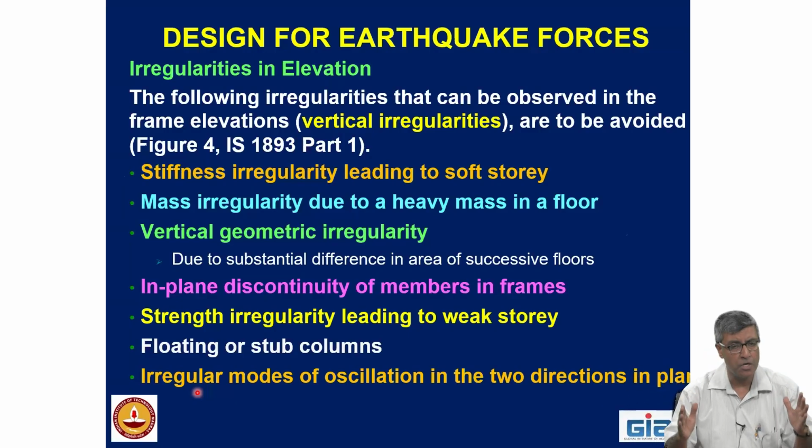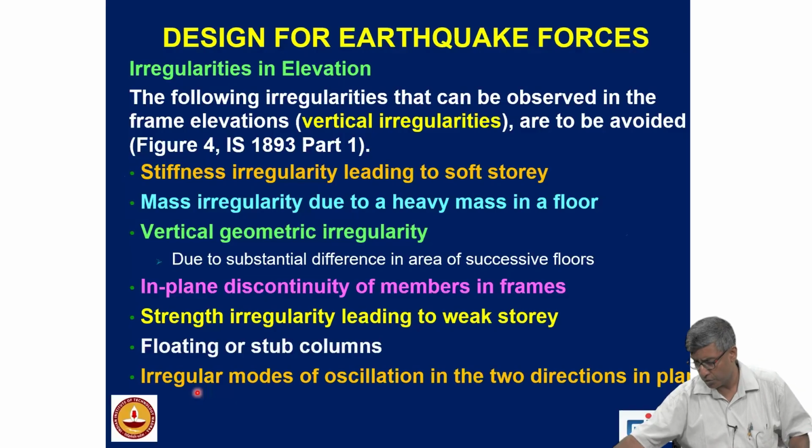I will repeat that we should have at least 2 frames in the 2 orthogonal directions, which are well defined frames. Okay. Floating columns or small columns can create trouble. Irregular modes of vibration also should be avoided.